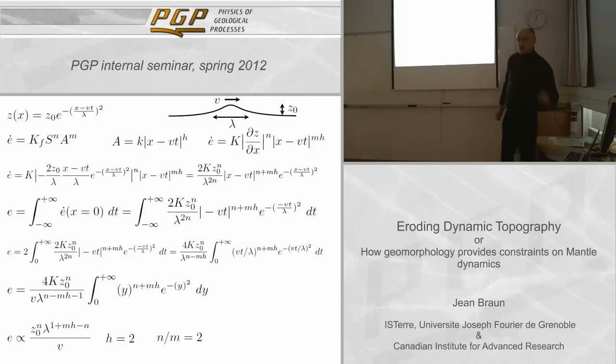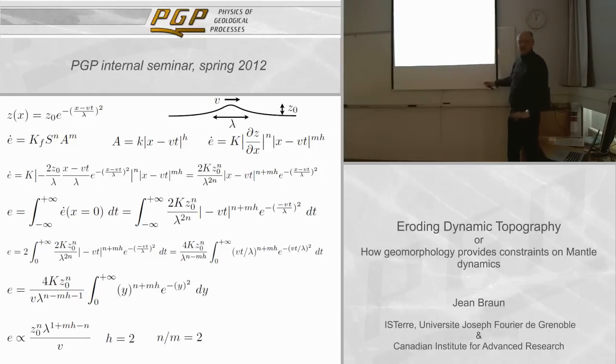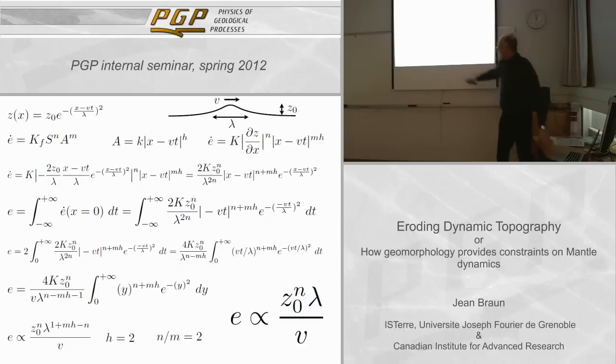But from the profile of a river, it's very well known, you can constrain the ratio between the two. And that's almost very close everywhere on the planet, almost equal to 2. It's called the concavity index. If you take that and put it in there, you can actually show that this cancels out for all values of m and n that satisfy that. And so you end up with this.